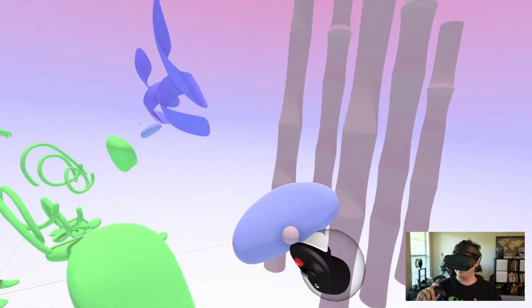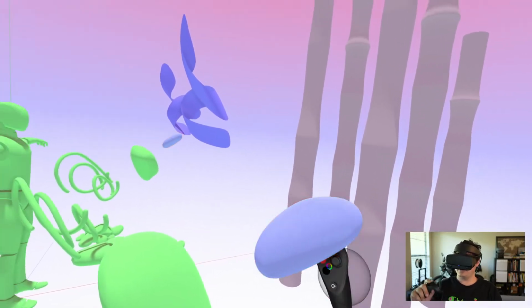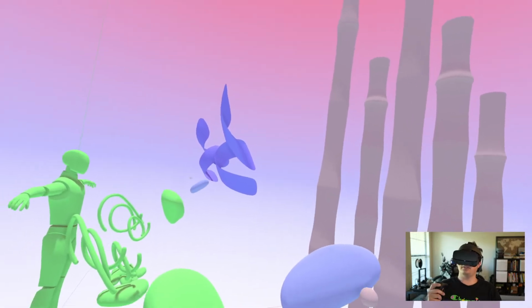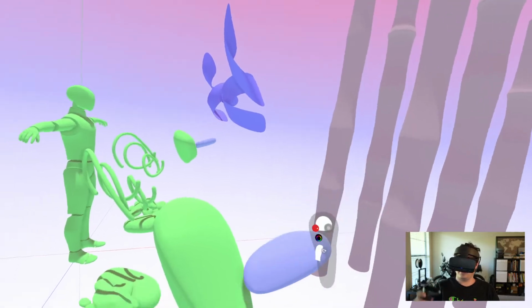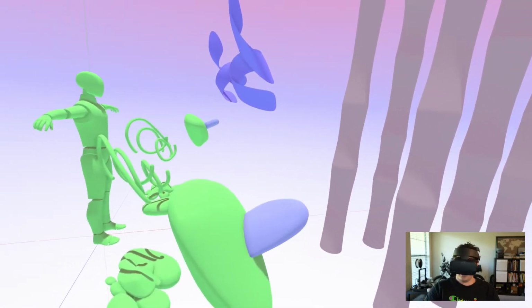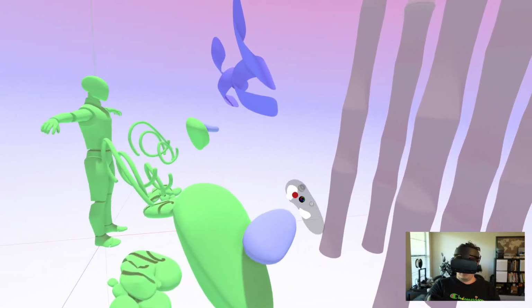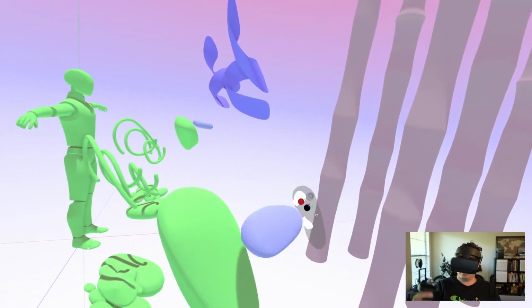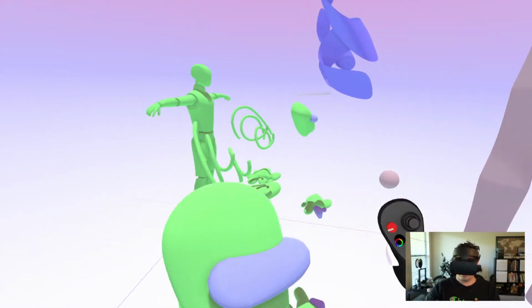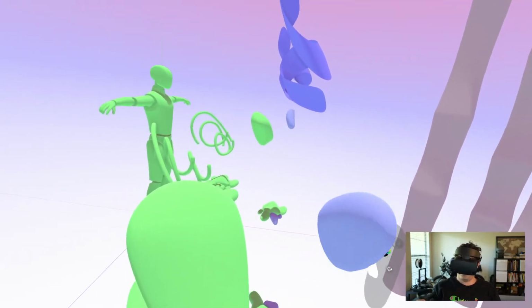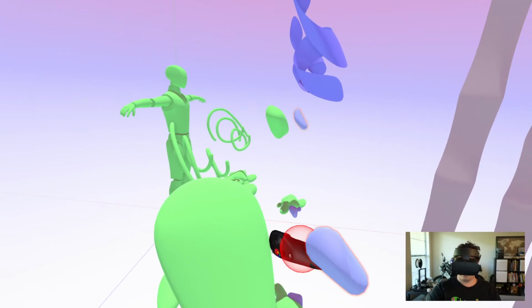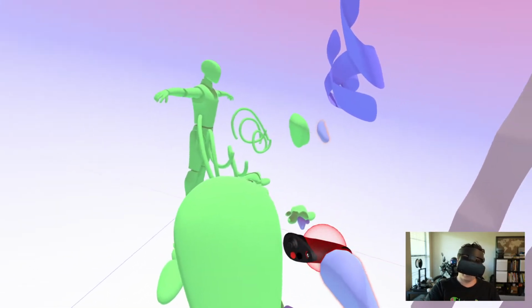Typically a Boolean is not even always cutting. It's sometimes joining things, or an intersection. But basically, you want to cut it out with this object. So this is the cutter, and you would intersect it, and it would cut that shape out of this volume, and this would disappear, and you would be left with a cutout right here.